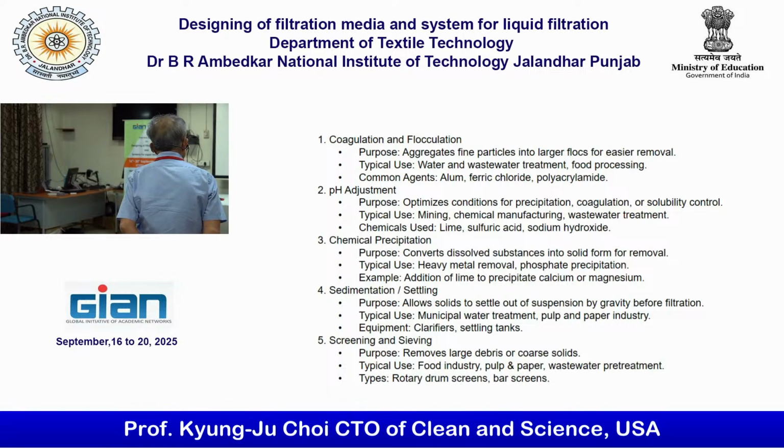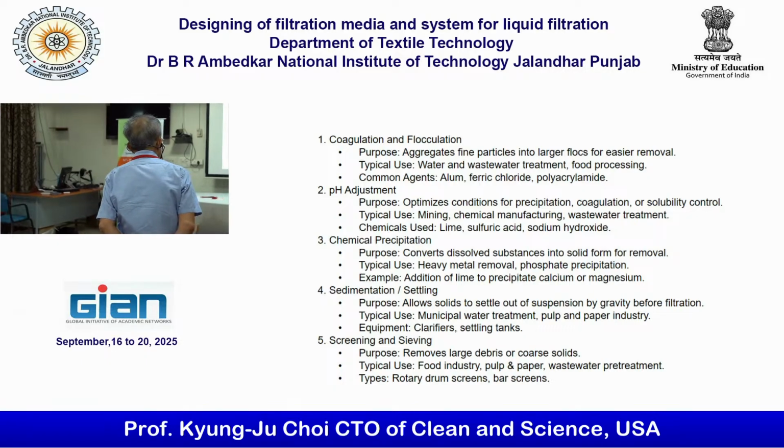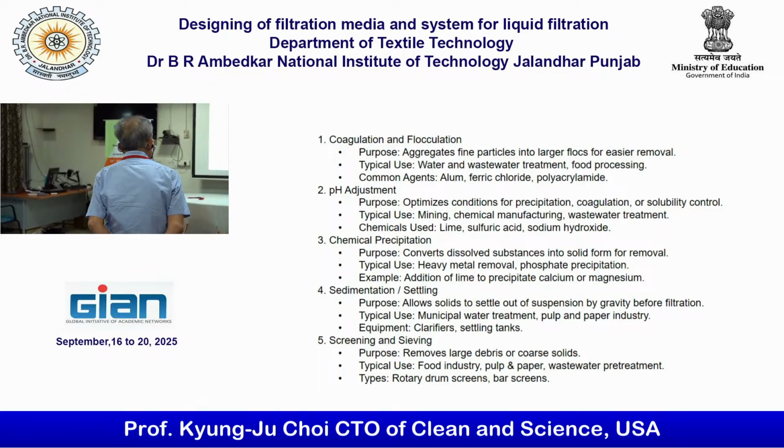Certainly the purpose is to turn fine particles into larger flocs for easy removal. The common agents, there are two of them. Polyacrylamide, that's actually flocculant, right? Ferric chloride, aluminum, that's the coagulant. Also, you have to do pH adjustment to optimize conditions. Used in precipitation, coagulation, mining, chemical manufacturing, and wastewater treatment.